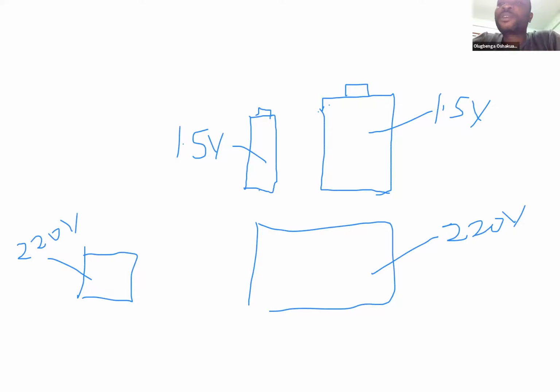By the time this small battery begins to issue out current, the voltage will reduce. It may be small, it may be large, but the voltage will reduce. The reduction has to do with the efficiency of the battery. The electrical explanation for why the voltage reduces is that the battery has something called internal resistance.